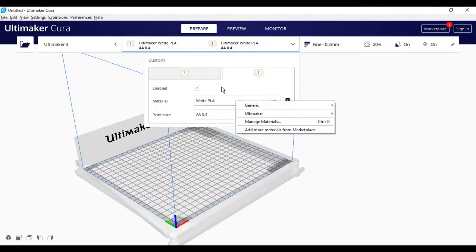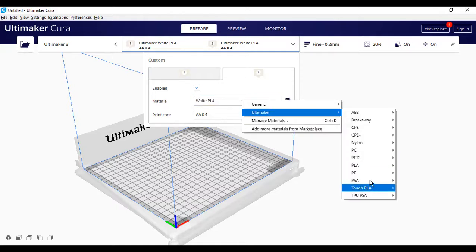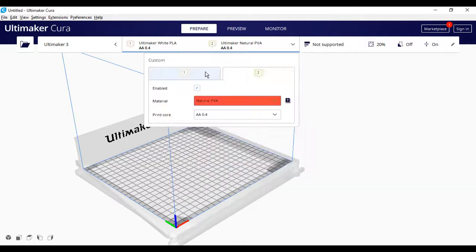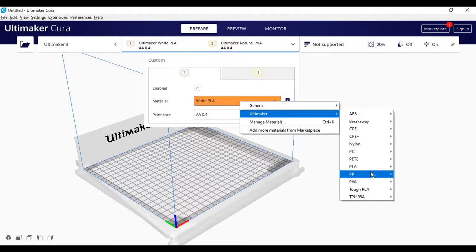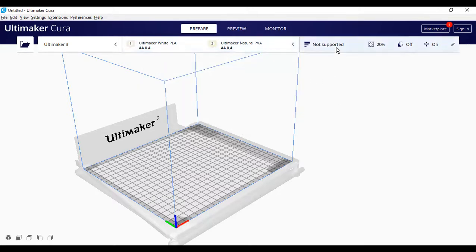If you are choosing supporting material PLA only, then we can choose, but we have to mount another roller, two separate rollers. Fine. If we have to provide supporting material, then we can choose PVA as well. But in this case it's not needed, so we are not taking that one. This is Ultimaker, this is PLA and white PLA that we are taking, right?